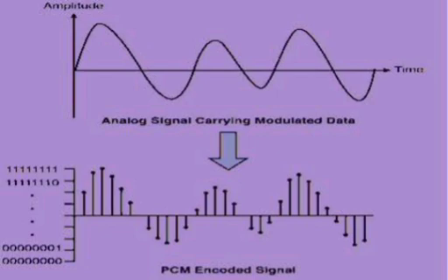Amplitude digital modulation schemes: ASK, amplitude shift keying. In this scheme, the amplitude of a high frequency carrier is varied in accordance with the digital data 0 or 1. For digital input 1, the amplitude level is high, and for digital input 0, the amplitude level is low. Signaling used is on-off signaling. Bandwidth requirement for ASK is bandwidth equal to 2 by TB, equal to RB. In ASK, the probability of error PE is high, and SNR is less.